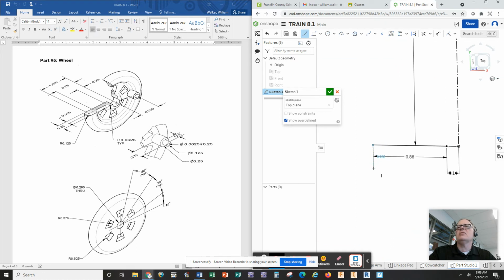I'm going to continue building this little cross section. So you'll notice over there, the thickness of the cross section is 0.25. And then if you come back, if you do the calculating, 1 inch minus 0.75 inches, you'll notice that the little comeback section here on this part of the wheel is also 0.25. And then there's a little inset here that goes halfway in on the wheel. Again, we're doing square corners to start. So if we go halfway in, that's 0.125, half of 0.250.